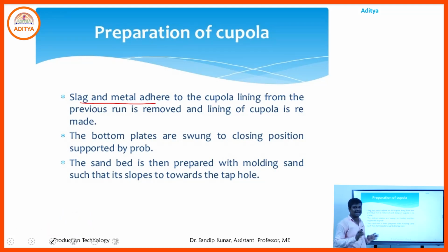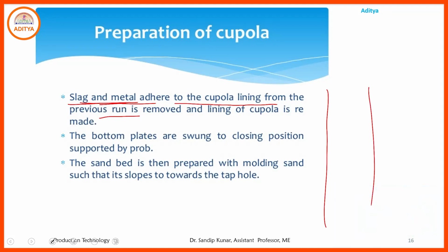Because it withstands higher temperatures. Before starting the operation, we remove the slag and metal stuck to the refractory lining surface.